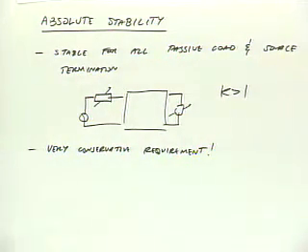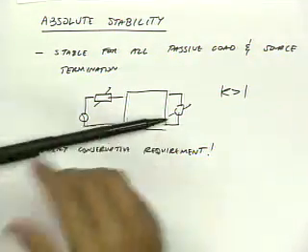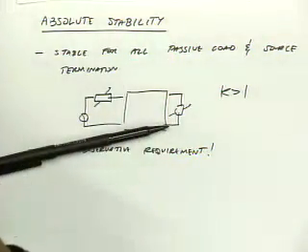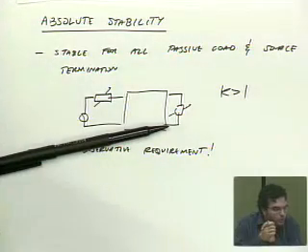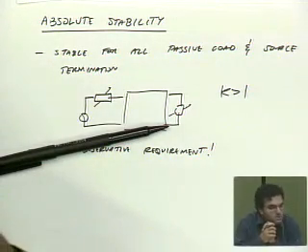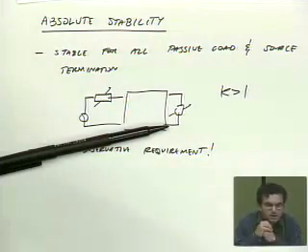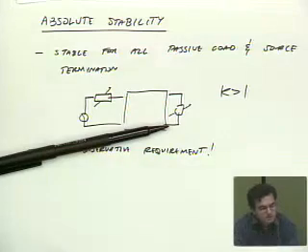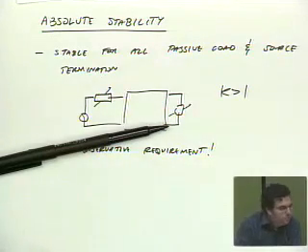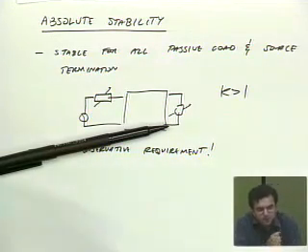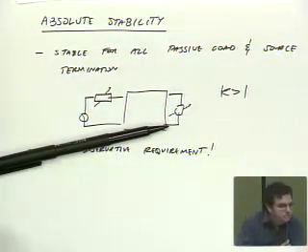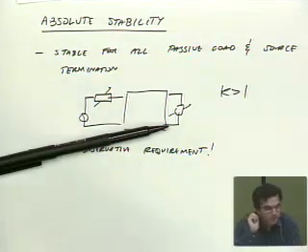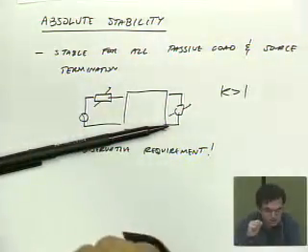because in practice the range of the load and source varies. So the idea is that if I'm designing an amplifier that I give to a customer and I say you can load it with anything you want, you can drive it with any source impedance you want, I guarantee it'll be stable. Then that means that k has to be bigger than 1. But then if I tell my customer, well, you know what, don't short the output. If you short the output, it's going to oscillate. Also, if you're driving it with a reactive source, yeah, it'll have problems. So if you're designing a general purpose amplifier that should work under all operating conditions, then you want this to be satisfied.